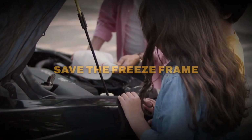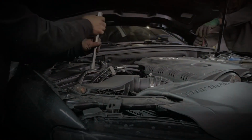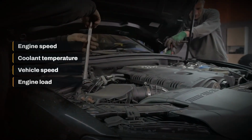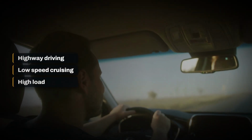Next, save the freeze frame data. Freeze frame is a snapshot of the conditions present when the computer recorded the fault. Depending on the vehicle, it may include engine speed, coolant temperature, vehicle speed, engine load, and fuel trims. That information can reveal whether the monitor failed during highway driving, low-speed cruising, high load, or another specific condition.